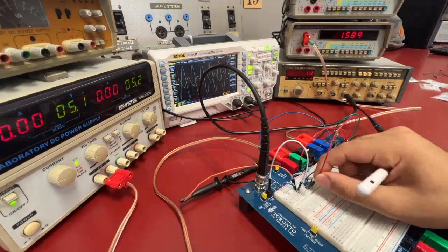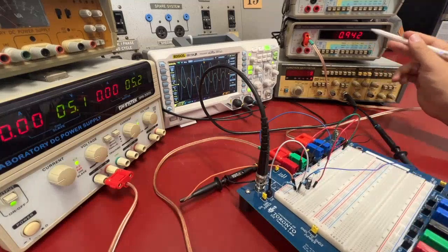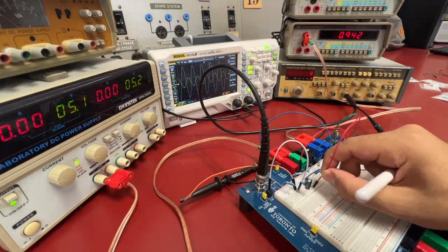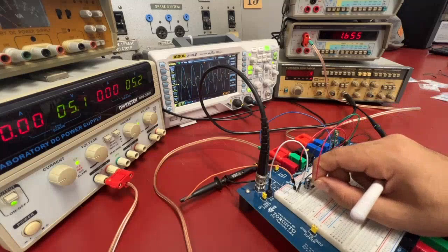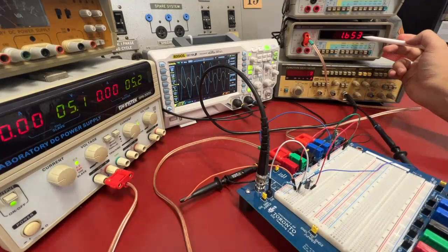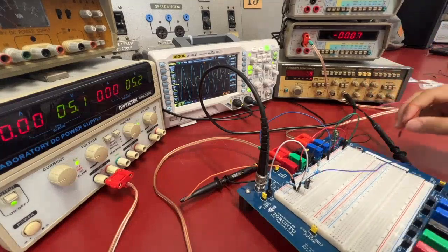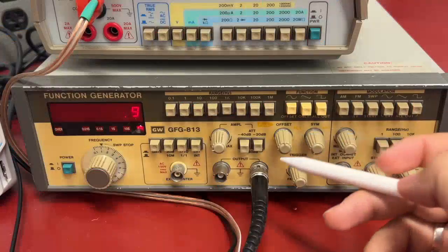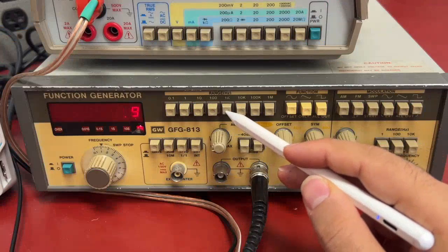Then the emitter voltage, also as expected, is around 0.9 volt. It indicates the transistor is properly biased according to our design targets. Also, you can check the collector voltage. 1.6 is consistent with the selected value for the collector resistance in my design and the target biasing current.